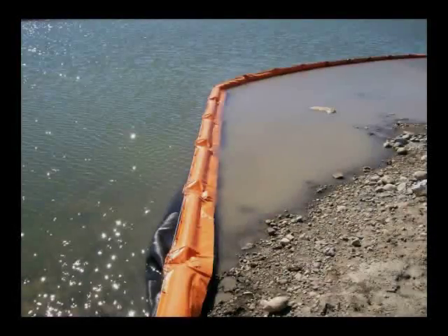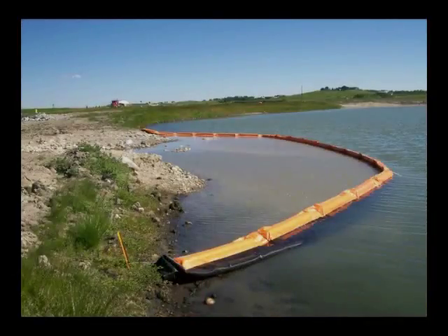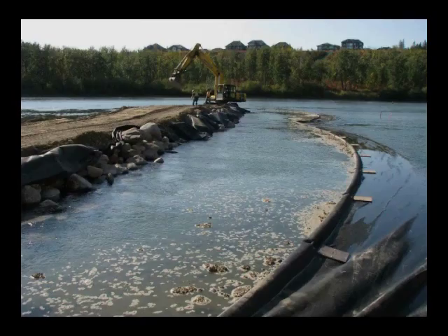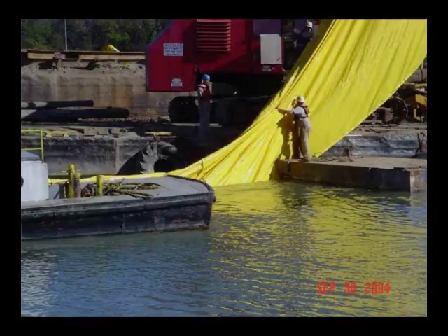Turbidity curtains provide temporary sedimentation control for earth changes that occur in water bodies. Turbidity curtains isolate the turbid water that is generated by excavation to a stream or lake bottom. Disturbed soils that settle along the bottom of a turbidity curtain must be removed from the lake or stream before removing the curtain. Before installation, verify that the turbidity curtain has enough depth to reach the lake or stream bottom.